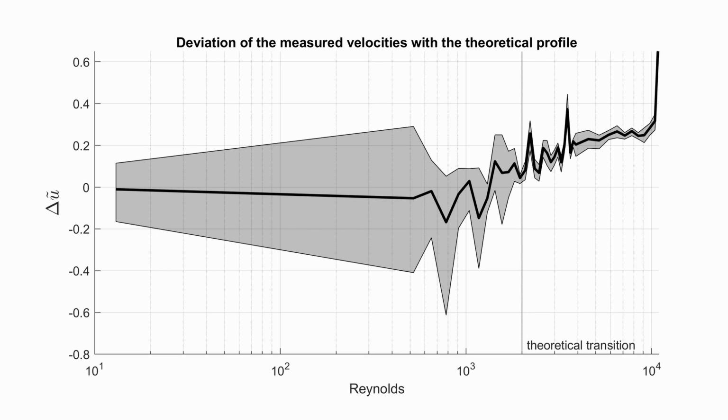Here we can see that around a Reynolds number of 2000 the flow cannot fully develop anymore. That is because the channel isn't long enough and the laminar flow starts to transition into a turbulent flow from this point on. With more tests and better test conditions, the test results could have been improved.